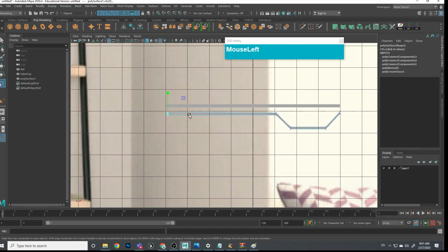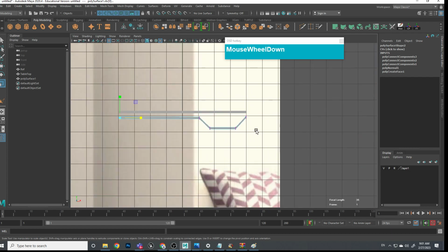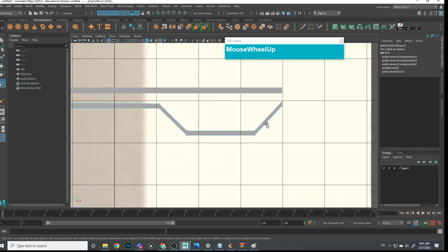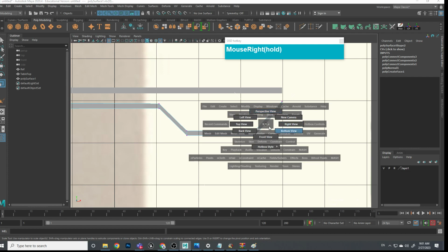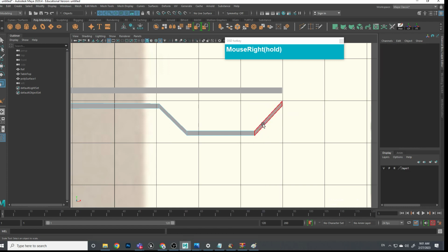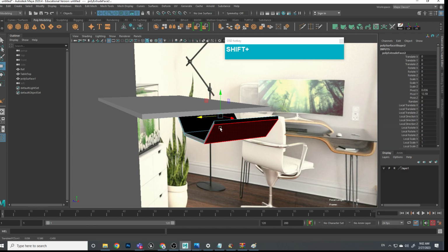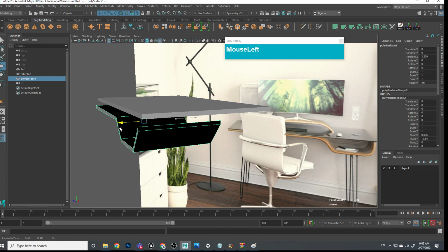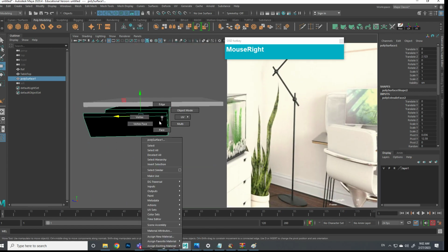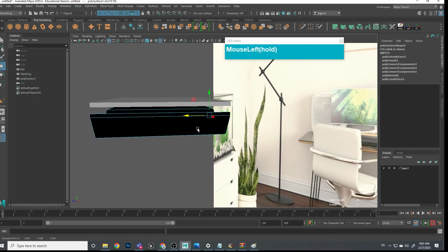Okay, so this is still a very simple object like that. And once we've done this, we can, let's see, we can extrude. Okay, so go and select all the faces by double clicking. Then using move, shift and extrude. Okay, then we can move this forward. Okay, and switch over to vertex mode and continue to move it back.